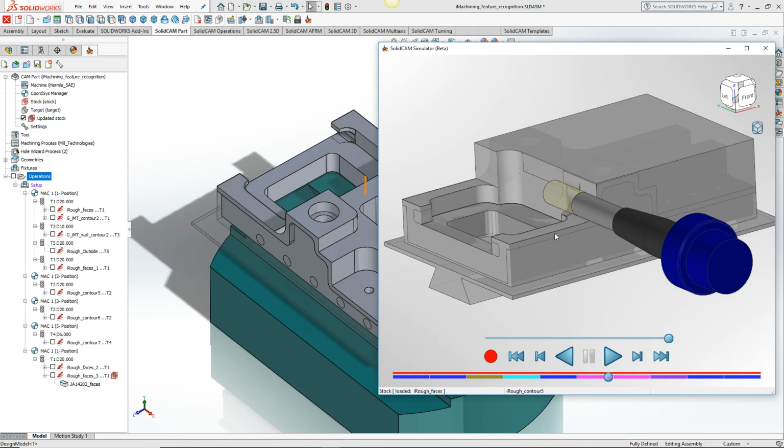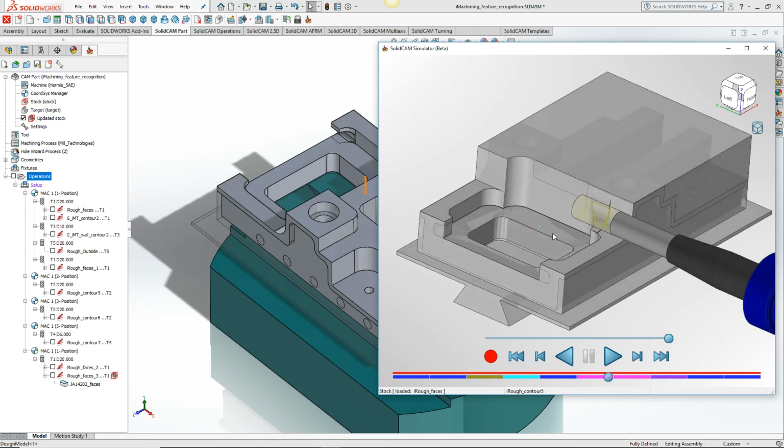And in the end, we always have the SolidCAM default chaining geometry to fall back on. So if you need to cut something that maybe isn't exactly on your model, you need to make a notch to touch off the tool on a probe or something on a secondary operation, you have all those tools with the normal chaining. So the feature recognition works great when you're picking off the model, but you also have the standard chaining and existing tools to do something outside of the feature recognition that isn't reflected in the model.